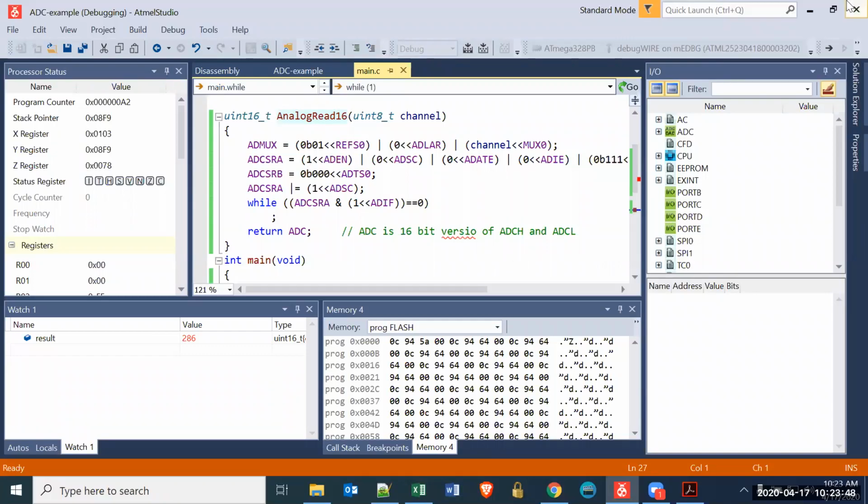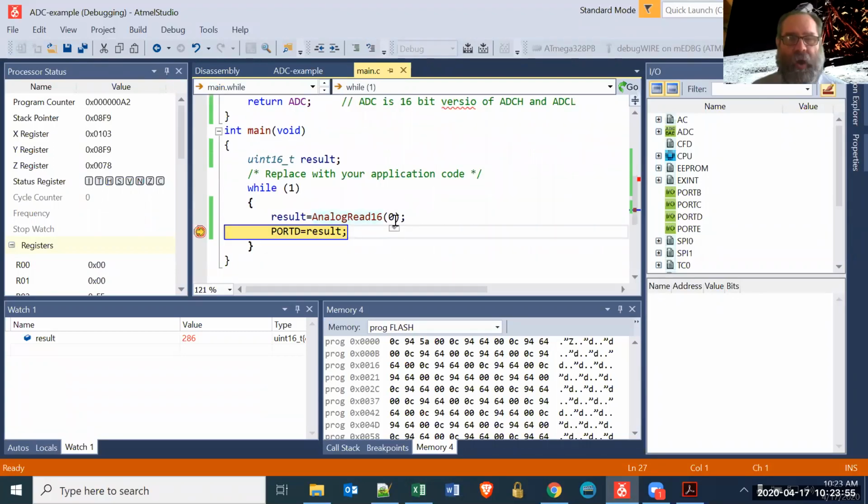So in order to control the other potentiometers, you just change it from 0 to 1 or 2? Yep. If you put a 1 here, you're reading the center potentiometer. If you put a 2 there, you're reading the leftmost potentiometer. That is correct. Which is one of the reasons this routine is really nice.